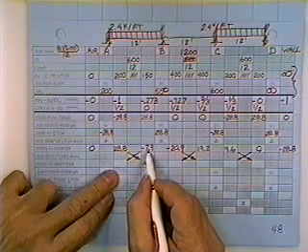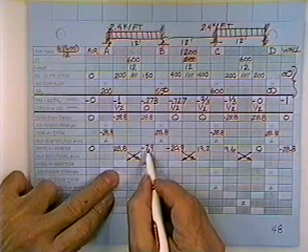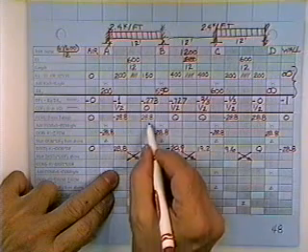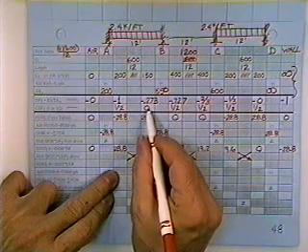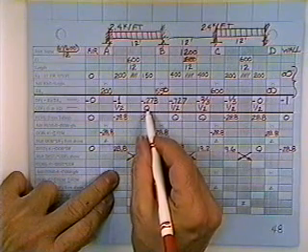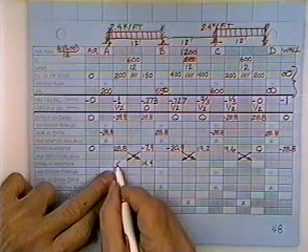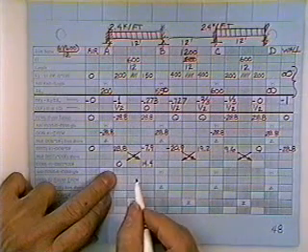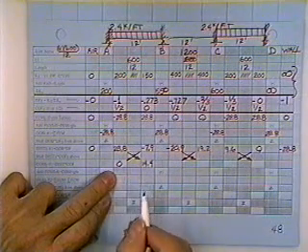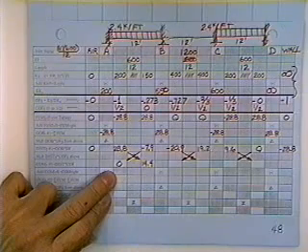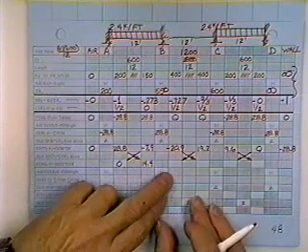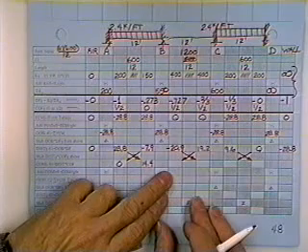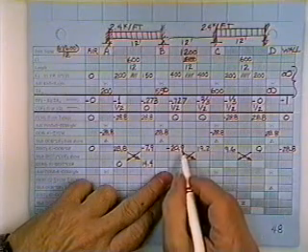How much of the 7.9 carries over to the left? You look directly above for the carryover factor. None. Well, that actually makes some sense because there's a pin over there, and so none of it can get to the pin. The pin wouldn't take any moment anyway. Carryover factor on everything else is a half.